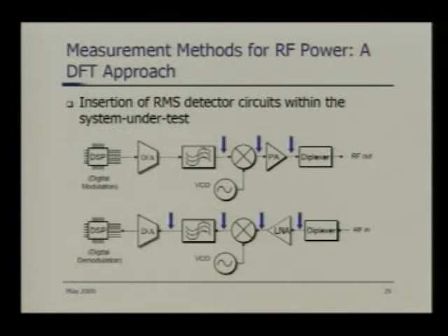it is going to swamp or overpower the receiver side. So what is usually done is that the output frequency of the transmitter is slightly offset from the receiver side. The circuitry that is used to multiplex in the frequency domain is called the diplexer. So if it is at 1.9 gigahertz, sorry, 1.9 gigahertz minus an integer multiple of 200 kilohertz or something, so that these are frequency multiplexed.